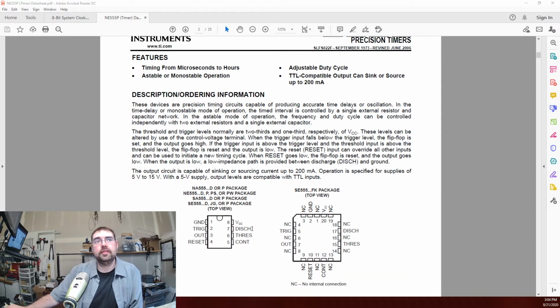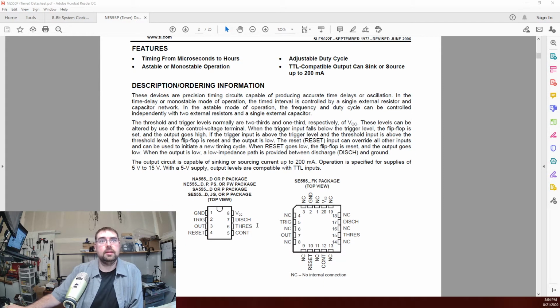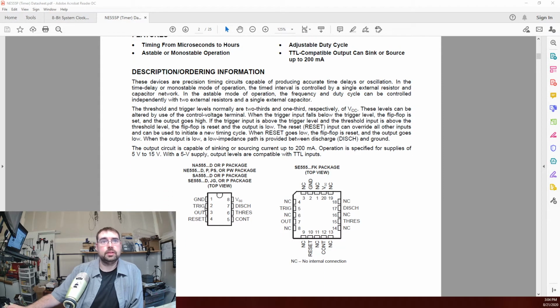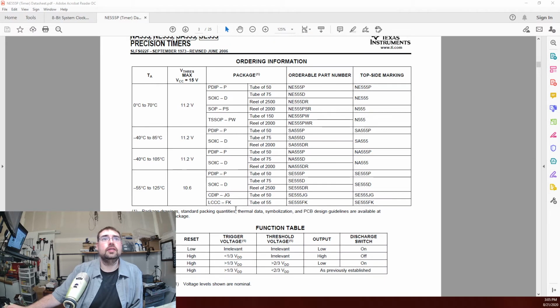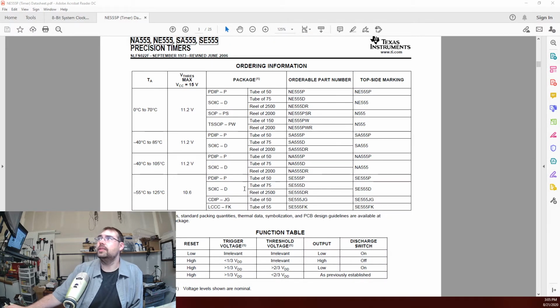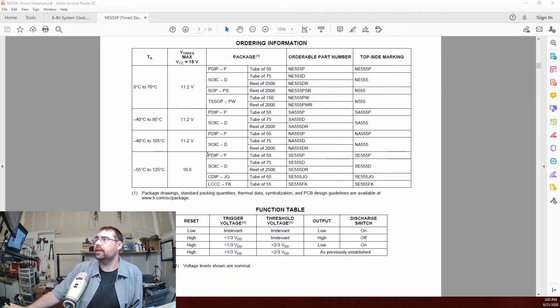Usually it'll start off by showing you what each pin is, what the name of it is, how it works. Sometimes it'll show you one that can go into a breadboard, and then it'll show you a surface mount version of it, depending on if they offer that. Some of them have a little more ability, but we're focusing on our simpler one right now. And then it'll show you what voltage and temperatures it can work at, what kind of tolerances it has for current, how it works, and what the functions of it are.